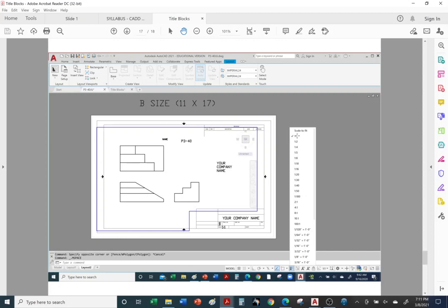But if this part is too tiny, then you want to go with something like 10:1. So if you're doing some electronic part, let's say for a phone, right? A small piece, you may want to increase it to 10 times, right? Use 10:1. Or maybe your part doesn't fit the sheet. If it's too large, a good example is maybe the size of your laptop or your computer. 1:1 is too large. You can go to half size or quarter size and so on.